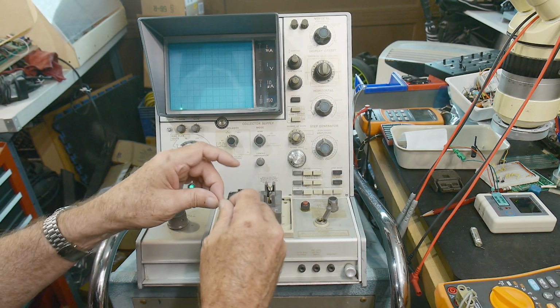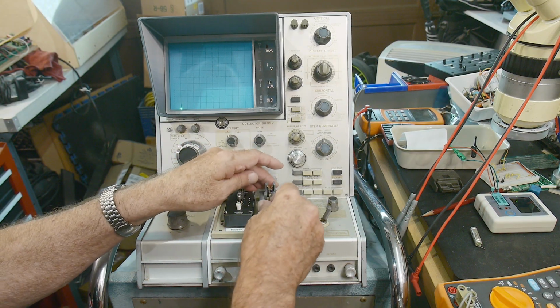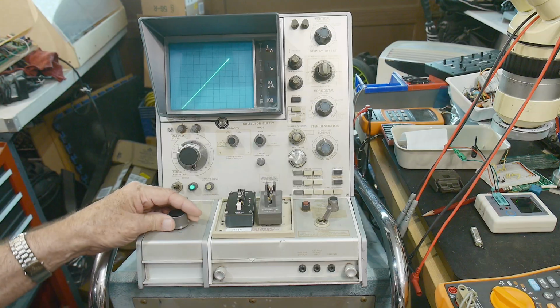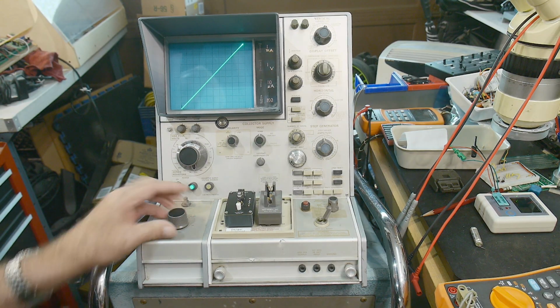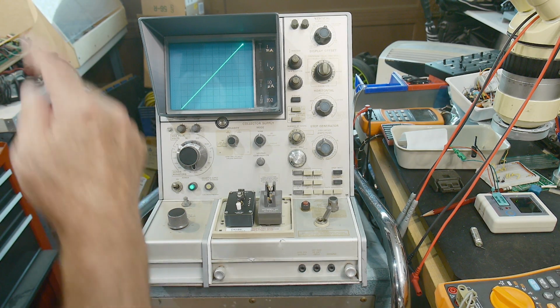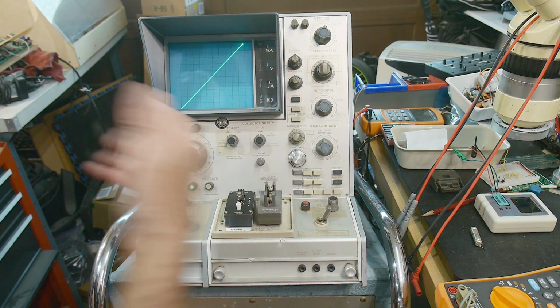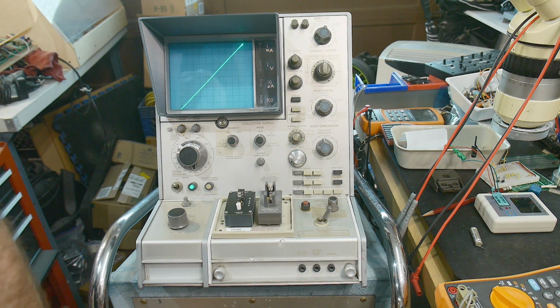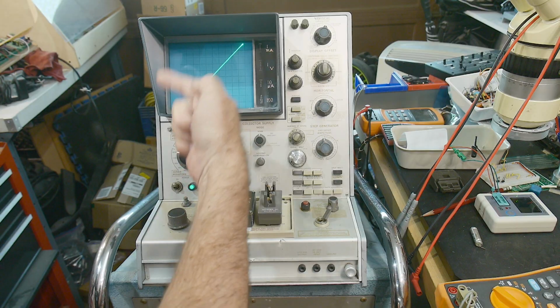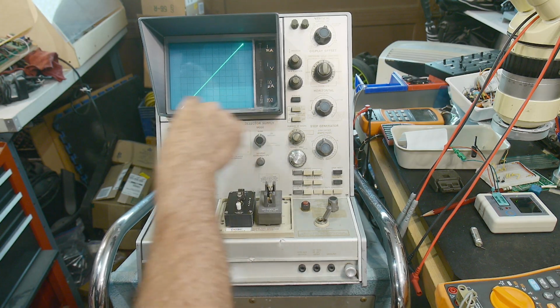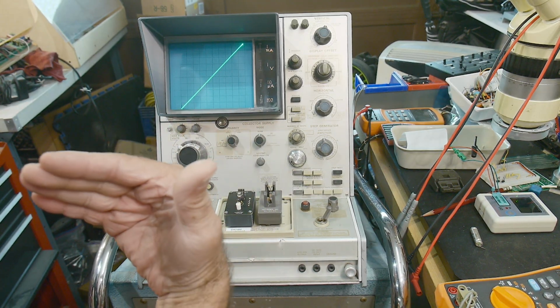So let's put in the resistor, and you can see what it looks like, and then I'll explain why it looks the way it looks. Well, it looks like a straight line. Why? Well, because remember, voltage equals current times resistance, okay? And so we're going to measure volts, and we're going to measure current at the same time. This is how many volts, and this is how much current.